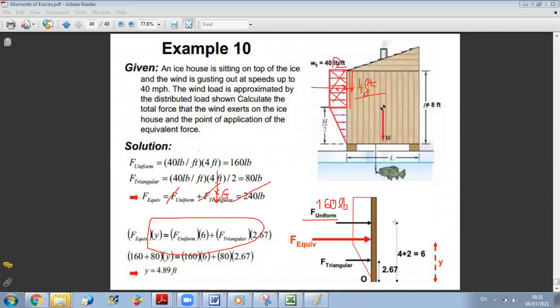So until now, I have reduced my rectangular load into one force. I still need to look at the second force, which is the triangular force. Just let me check here. Okay. Now, for the triangle, I want to do the same job. So first, I should calculate the area of this triangle in order to find the resultant force.